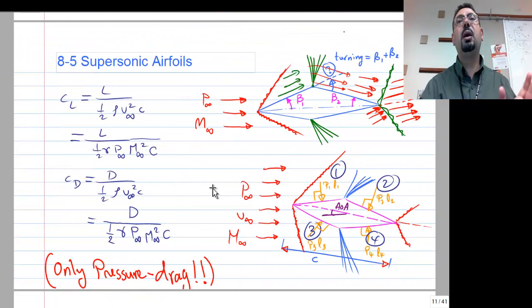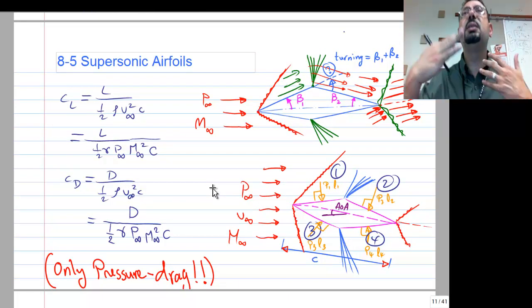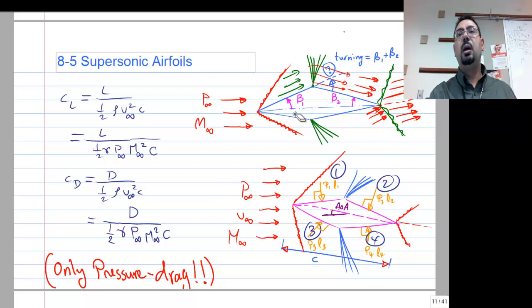So things become complicated when they start having a lot of surfaces, but it's the same idea. Okay? Same idea. Basically, you try to find out shock or expansion, shock or expansion. This will always have expansion. There is no question that here, in this diamond shape, you will have expansion here. Why? Because you suddenly have a lot of area. So you can count on two expansion fans.